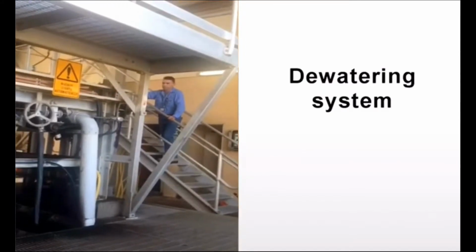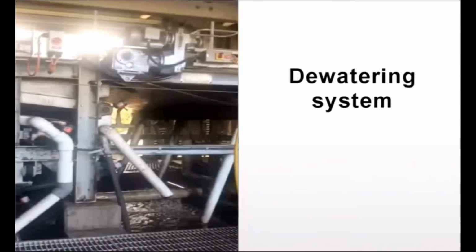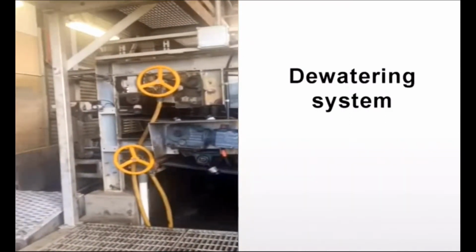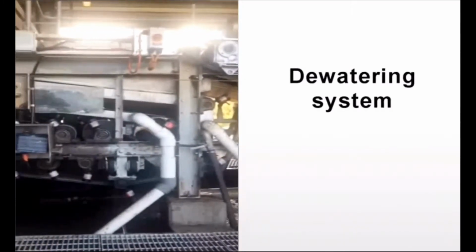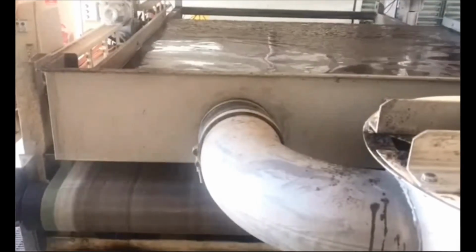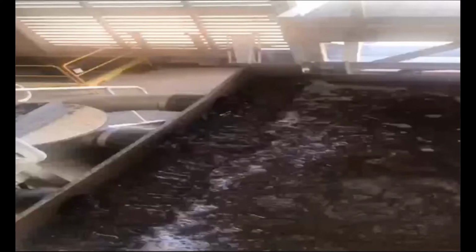The activated sludge produced after reaction of phosphorus and carbon species is transported to the dewatering system after settling. This is due to excessive sludge. In order to improve transportation efficiency, the burden on the reaction vessel is reduced. So, here the sludge and water will be subjected to the final separation. First, the white sludge is spread from the pipe and falls on the filter cloth. The filter cloth has a lot of fine pores, and a part of the water can be filtered out in this process.